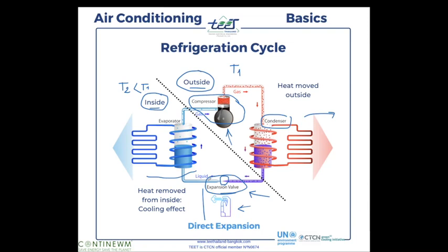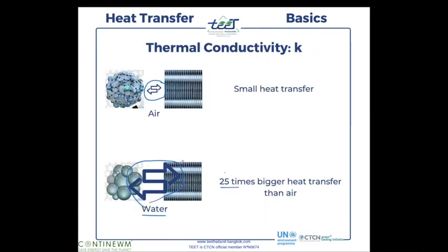The evaporator is the place where you have inside the refrigerant fluid and the metallic fins, and that is where the heat transfer happens, where you have the heat from the water and the air, okay, that is transferred through the copper of the metallic fins of the coil to inside the refrigerant fluid, okay? So since inside this coil, let's go back here.